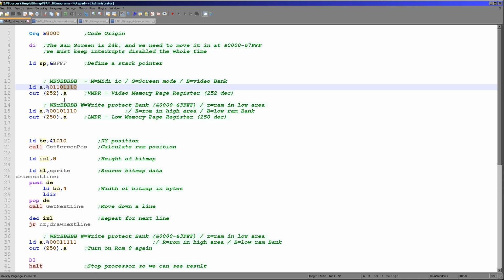So why are we selecting 14 and 15? Well, these are the last two banks of a 256K system, which I believe is the lowest specification. There was a 512K system, but that might not be available. So by using that, we've got tons of space for our program code, but we've got these two paging banks within the reliable memory that we know will be in the system. So we're just writing that here.